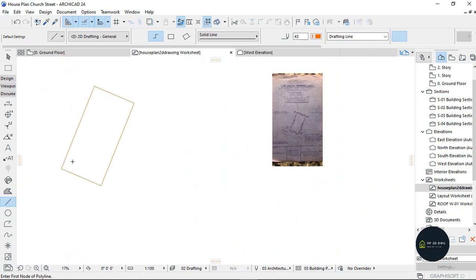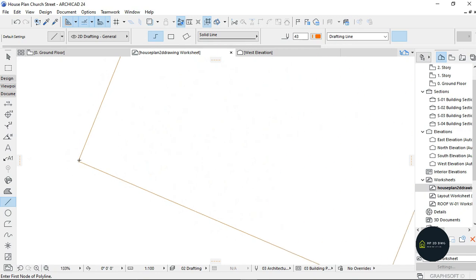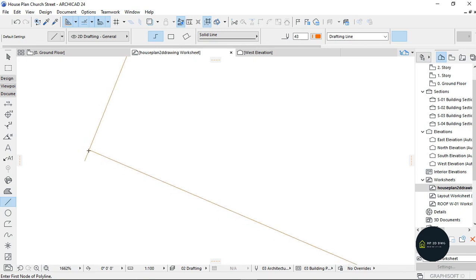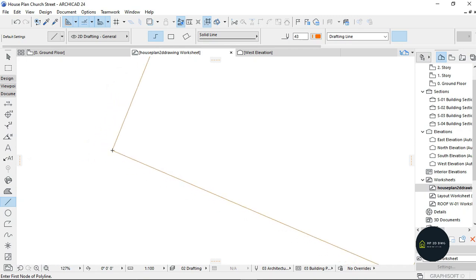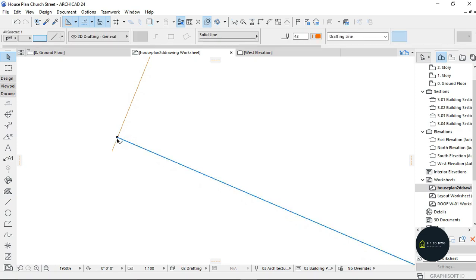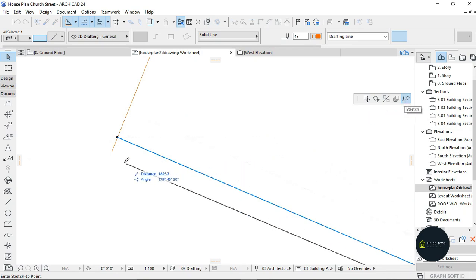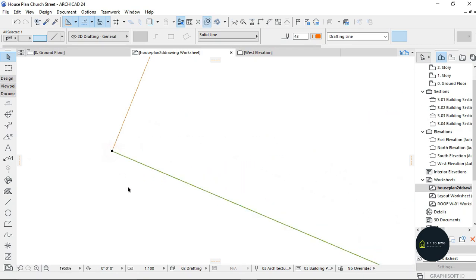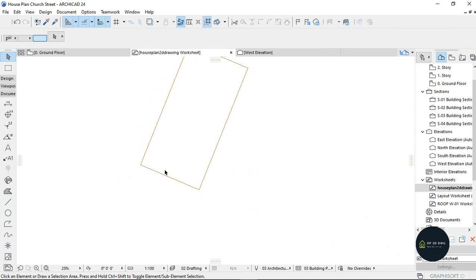One problem that we always notice in some of our drawings is that it doesn't always link together. One is always off, one is always on. So you know what I'm talking about. What I do is, I click on the line, I click on this, and I make sure I select stretch, and I just select that point there. I press escape, then zoom out.